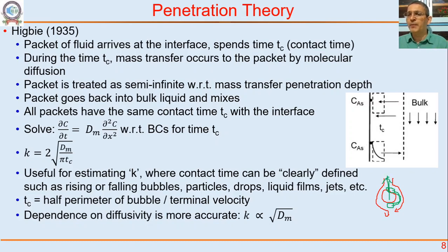Or it could be a solid particle which is settling down. Exactly the same thing will happen. Solid particle settling down. Remember the sugar problem. The liquid is going around like this. I told you that the relative velocity is the terminal settling velocity. That's why the relative velocity is the same as the terminal settling velocity.